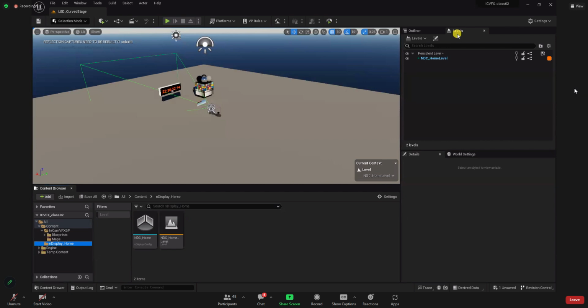There are two ways that a level can perform. It can perform as it does by default as a blueprint, the basic building block underneath all the other building blocks in Unreal Engine, or it can be set to stream, and that's what we want to do.